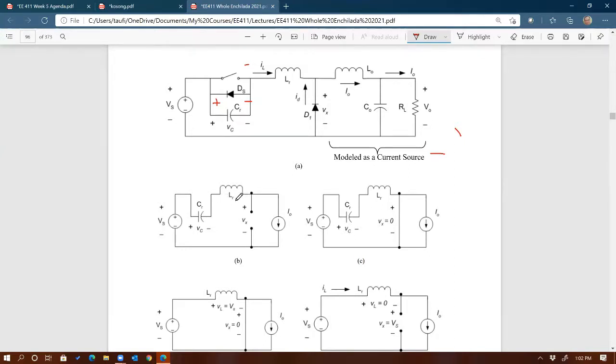So we know that if there is a constant current flowing through the inductor, that means the voltage across it is 0 volts right here. How? VL is equal to L dIL/dt. So don't forget, VL is equal to L dIL/dt. If dIL/dt is 0, because we have a constant current, therefore the voltage across the inductor is 0. If that is the case, then KVL states that the voltage across the supply right there is equal to VC plus VX, right? Agree? All right. Now that's the first question.